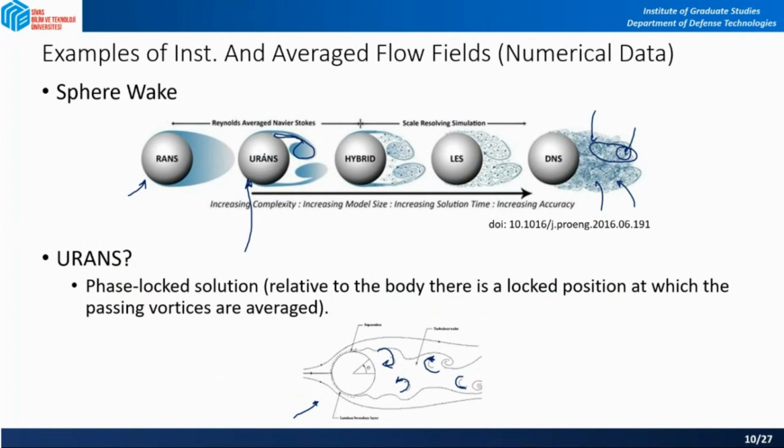So you are able right now to see that if the process is steady, then you know that the time average and ensemble average are the same, right? That's why if you solve a steady process with RANS and with URANS, you will get the same thing. The URANS only matters for unsteady processes.